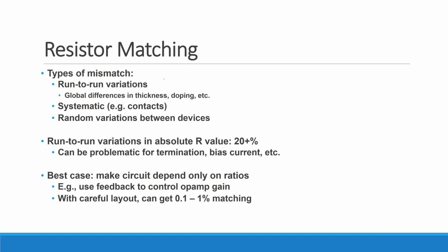Okay? So again, if I just took some resistor and I built it on a chip and I fabbed 100 or 1,000 or 10 million of these chips, and I looked at what's the value of those resistors, what you'd actually see is you'd get some kind of Gaussian distribution. Sometimes it's not even Gaussian, but you get some sort of distribution there. Okay? So you never get exactly the value you wanted, but you get some variations around that.